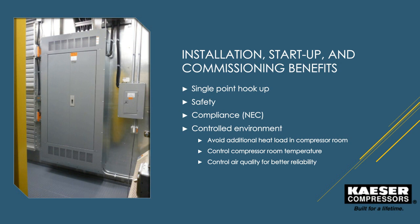Another benefit is controlling the environment. With a properly designed and sized package that includes a properly sized exhaust duct, we are able to evacuate all of that heat generated, and therefore we can regulate the internal temperatures of the room. This is imperative when designing a compressor room, because this is usually your pass or fail with the temperature-related items.